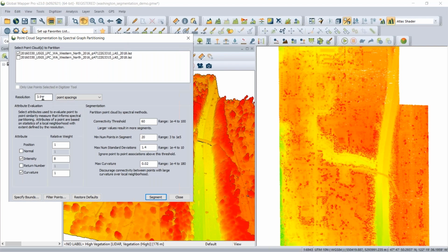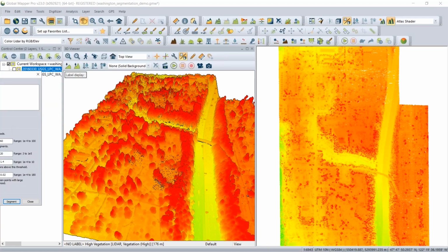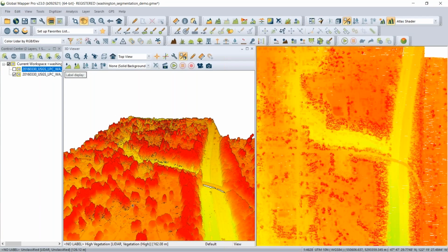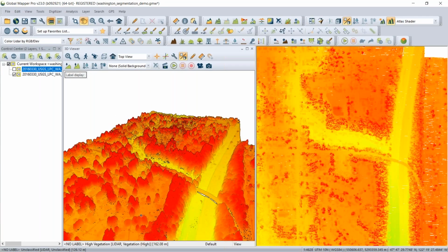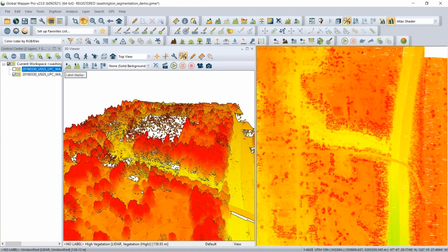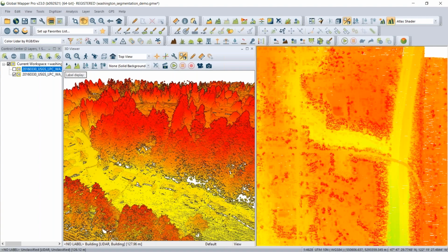So with this particular data, this is higher quality publicly available data. It's about 0.2 meters between points here, so pretty detailed. You can see I've got some buildings and trees. I've got a big highway here. There's also a lot of residential area here. Let's zoom in a little bit so we can see that. We've got a lot of buildings and trees. And as we look at some of these different attributes of the point cloud, you'll see that there are ways where I can really get some detailed classification here.